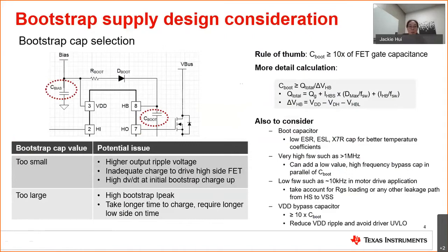It cannot be too small, because if it's too small of a value, it may not be able to hold enough charge to power the high side MOSFET when it needs to be on. A small cap also leads to a potential high dV/dt when it's charging up, which can potentially damage the HB pin in here, which then will damage the driver.